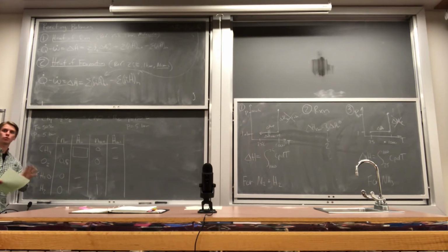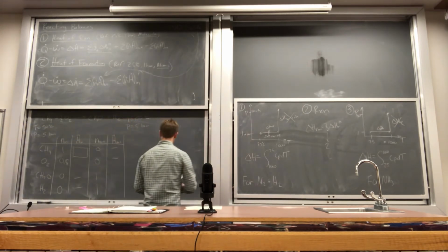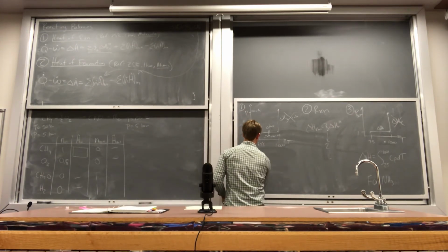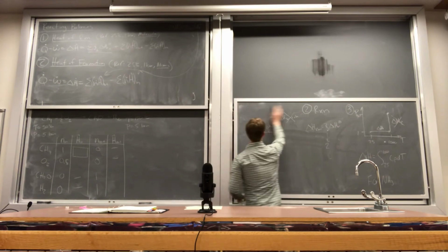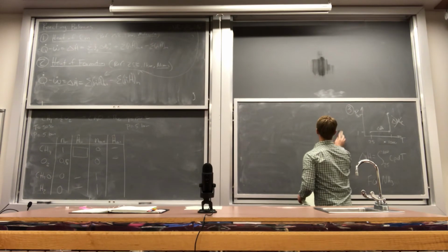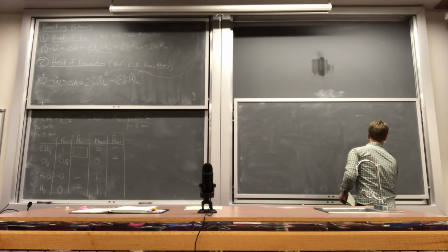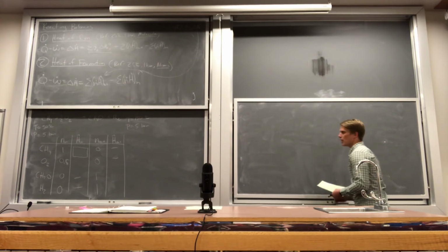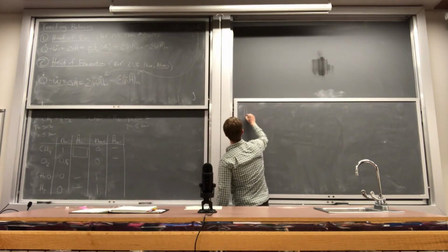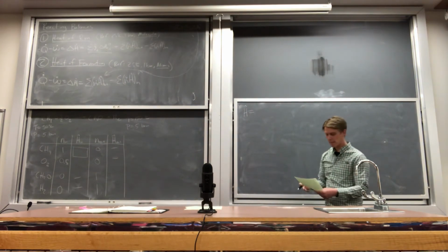So the heat of formation approach is really nice because it is the same formula for every single species in the system. For this particular one, because they're all gases. The boiling point of formaldehyde is about, I want to say, minus 20 Celsius. So all of these are gases. For every single species, the enthalpy formula in this particular problem is going to be exactly the same.